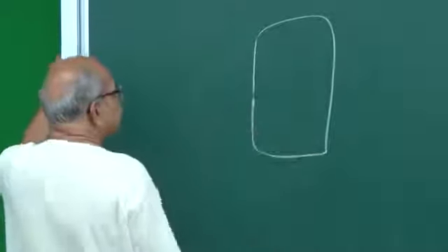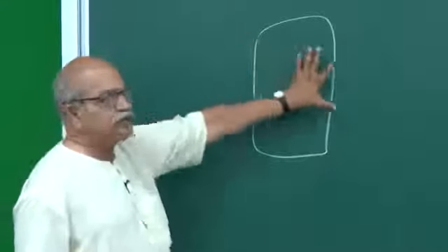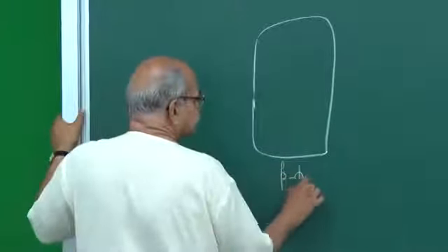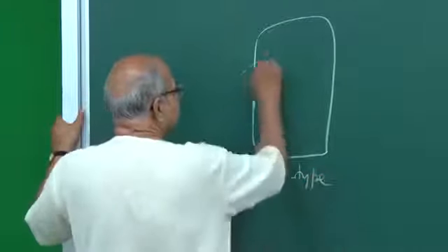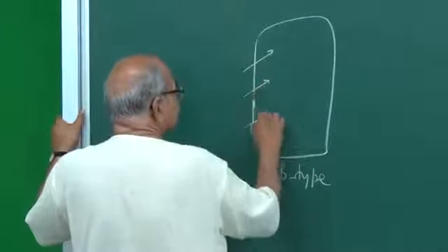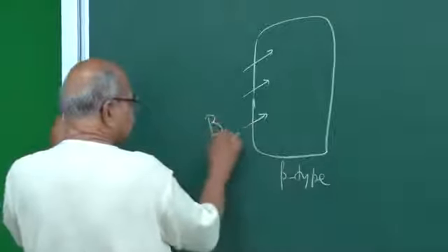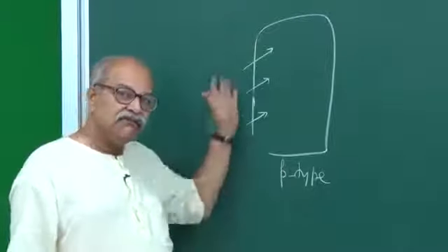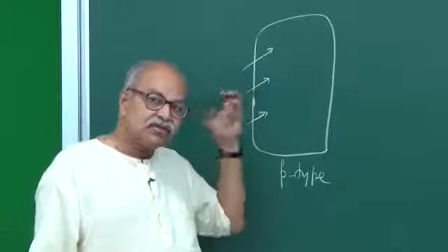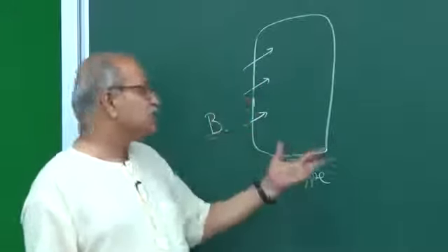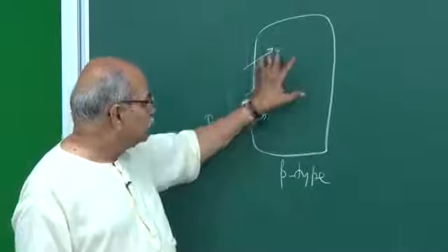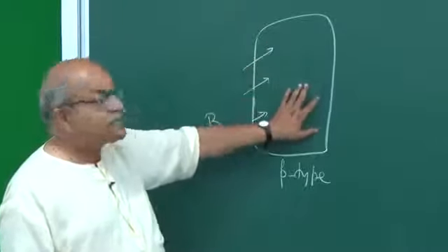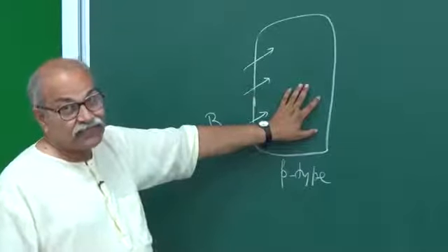So, that is the starting material, and with this starting material, the first thing is this entire wafer is made either p-type or n-type, this whole thing. So, let us say we make it p-type. To make it p-type, you have to diffuse trivalent impurity like boron or something. So, it goes there. Here also you have very controlled processes. There are several processes by which you diffuse these impurities, and at the end you retain that silicon crystal.